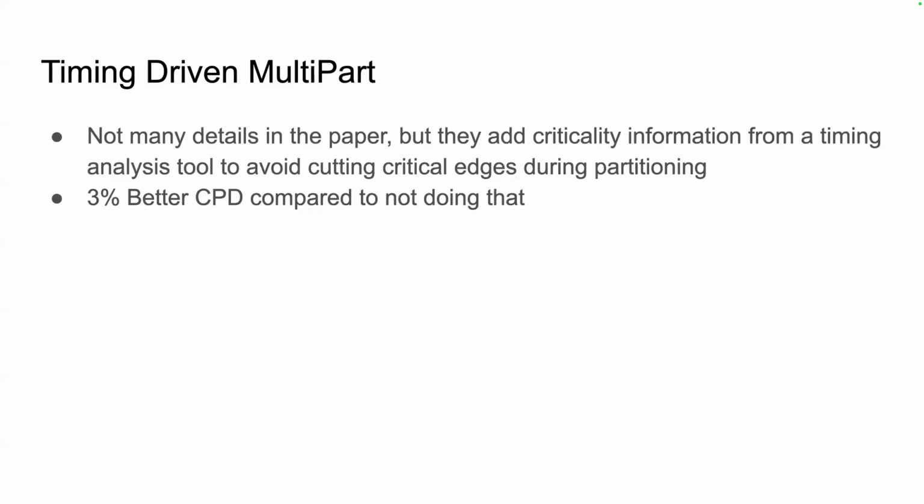But I haven't looked into that. If you really did a timing analysis of the whole graph, you could get basically the arrival time at every node that you're cutting when it's going in, and you can mark that as your set input delay, and you get the downstream time, like kind of the required time. So the required time is almost whatever delay is coming after your output, you mark that as a set output delay, and you're essentially modeling what's happening in the rest of the netlist now. So by putting delays on your inputs and outputs.